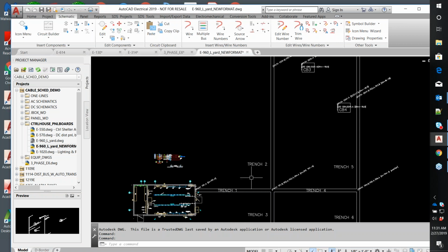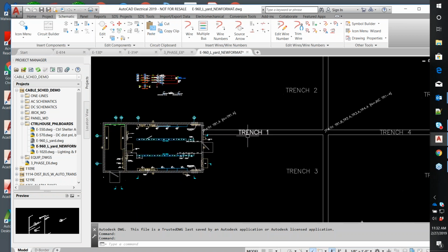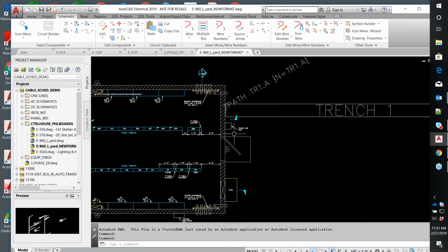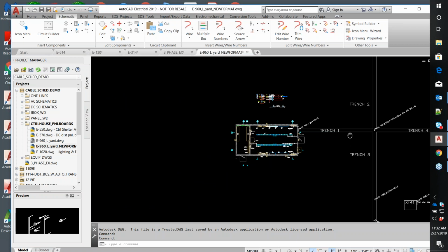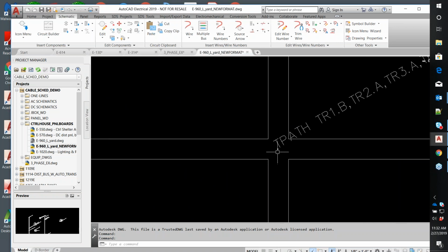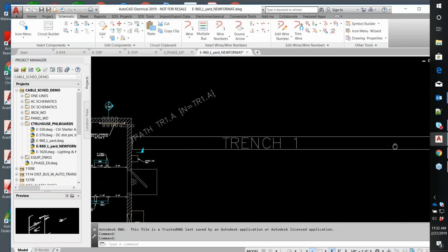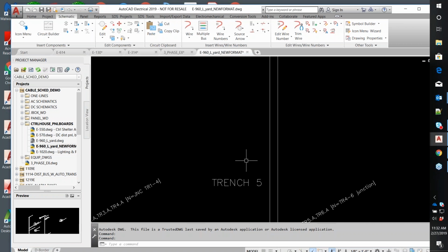Now, this is a tool that's been recently developed by SBS for doing cable routing and cable length calculations and cable voltage drop checks. So let me quickly give you an idea of how we made this work. We have just a generic AutoCAD 2D drawing to scale, and we've added what we call work points at junctions of trenches and at beginning and ending of conduit runs.